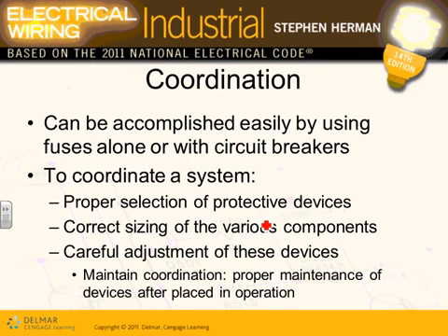This is probably the second time we talked about the current characteristic curve. In a couple of weeks, you're going to hear your friend Chad standing here using SKM PTW to do this coordination. When you do overcurrent coordination, if Karen were to go right now and short one of these lights above your head, you want the circuit breaker in this panel right in this room to trip, not the main 3,000 amp fuse in the basement. That's what coordination is.